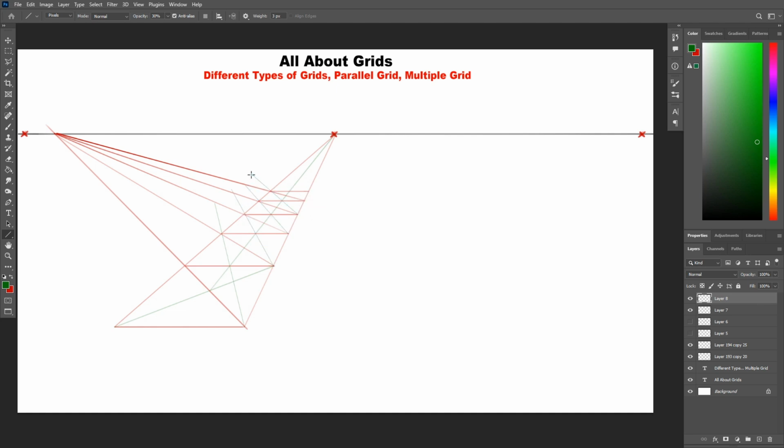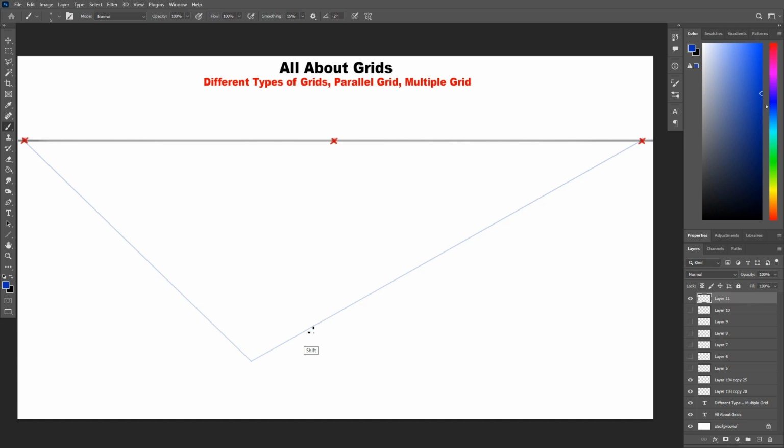Let's now do a 2-point perspective rectangle and see how we can use the same method to draw a quick grid. Let's draw the rectangle first and then connect from one corner to the other all the way to the horizon line. Here the angle won't be at 45 degrees since it's a 2-point perspective unless you use a 60-degree cone of vision connected to a stationary point.